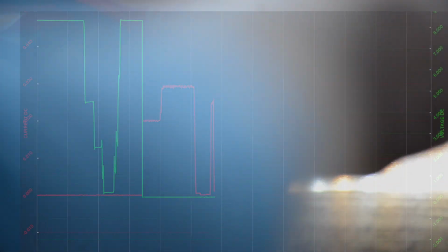And because they're in series, KCL tells us that they must be sharing the same current. So we're only as strong as our weakest link. If I pull one cell out, current crashes to zero. If I flip one over, now it's really zero. It was a little bit before. Bring it back in. Try the other one. So current is much more sensitive to light intensity than voltage.